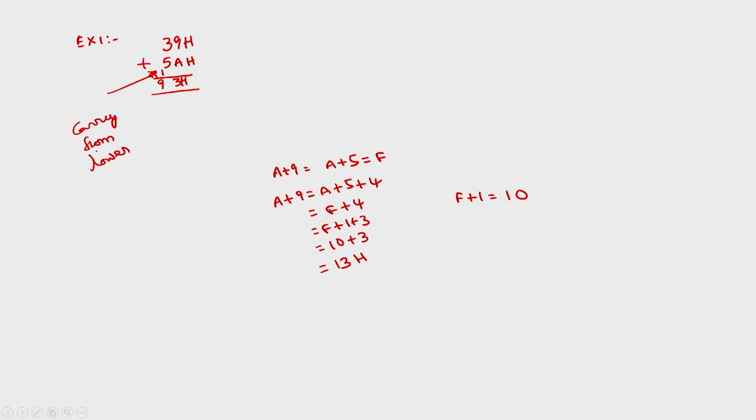This is lower nibble 9 and A. It implies the auxiliary carry flag is set. We can also check that there is no carry out of the MSB, so it implies the carry flag is reset. We can also do this using binary.